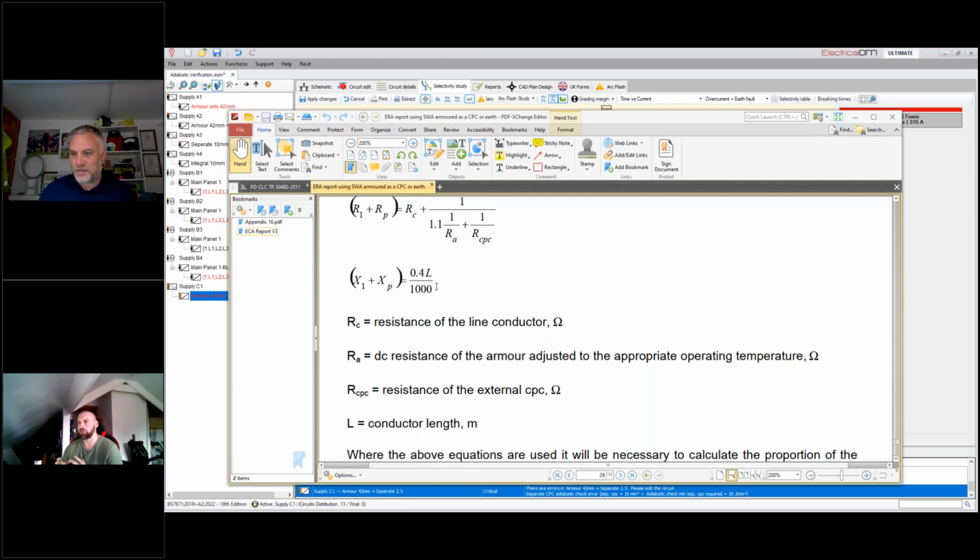So on smaller conductors, where you have impedances that are genuinely higher than what this value will be, you're going to be fine. It's when you get really low impedance, so large cables, even short distances, that are usually more of a problem, because naturally those will have lower impedances as well.